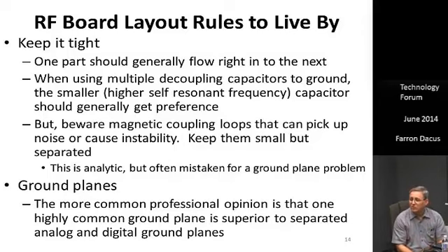And the ground plane you're using for the whole board might not be the one that's appropriate for a certain impedance you want. Like suppose you've got a couple of amplifiers that by their nature are closer to 100 ohms than 50 ohms output. And instead of wasting parts converting them to 50 ohms, maybe you want to run a piece of 100 ohm microstrip at a different distance, different depth from a ground plane you've set up for nominally 50 ohms in other places.